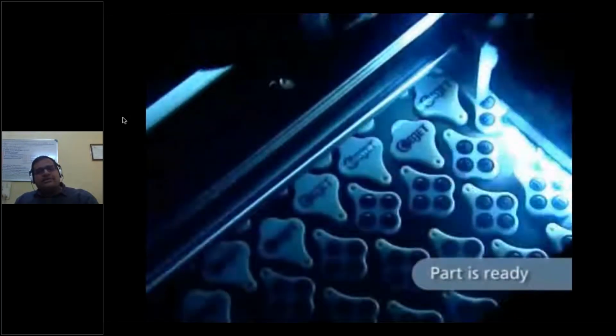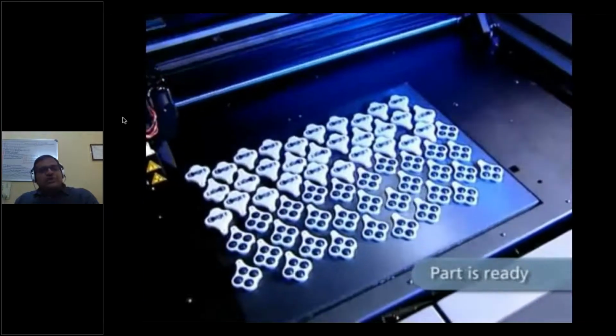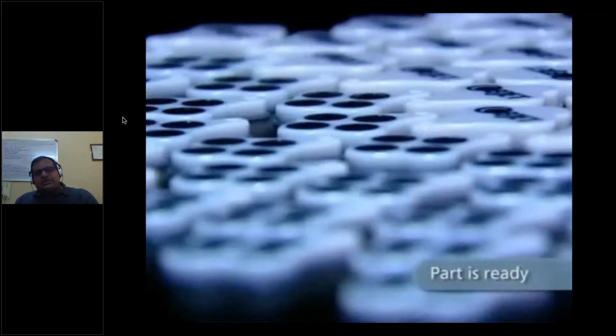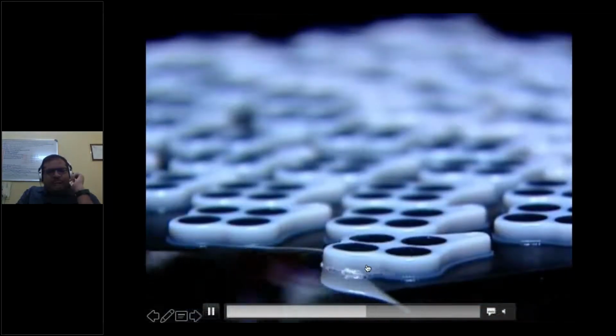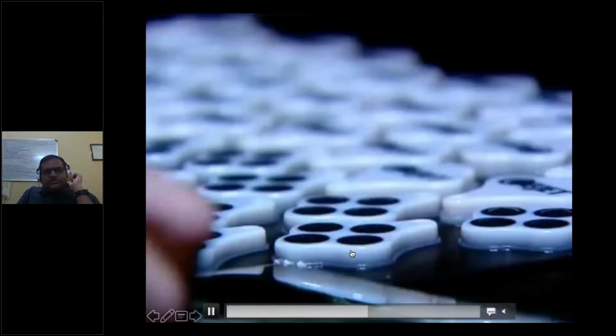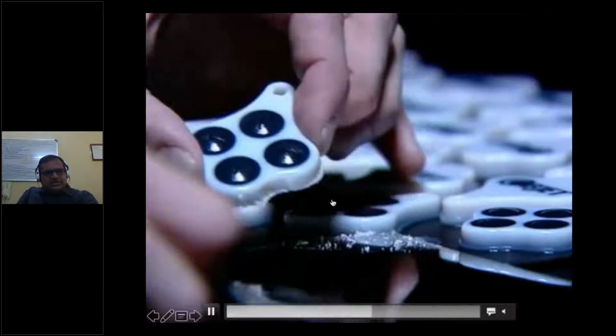Because you have more flexibility in jetting the nozzles, you can vary the material. How will you be varying here? You have two materials here. It's not only color, I'm talking about different properties of the material which you are going to jet. And for the support structure, something like a wax, or a wax-like material, will be used as support, which you can see at the bottom.